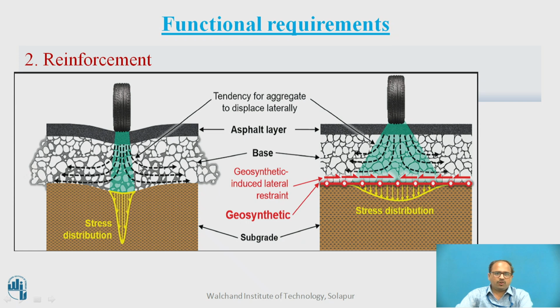Then there is a tendency of aggregate to displace laterally. So if I place one geotextile here, in between base and subgrade, in that case your load distribution is equal.